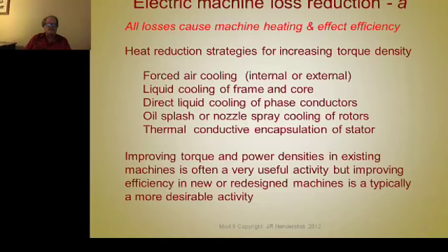In large power plant generators, hydrogen and nitrogen is used to cool stators with long diffusion paths through these spaces. We're going to look at some of those parts later, when we study the lecture on cores and laminations. We'll see some examples of those cooling vent passages through the cores. But all those things improve the torque density of the machine.